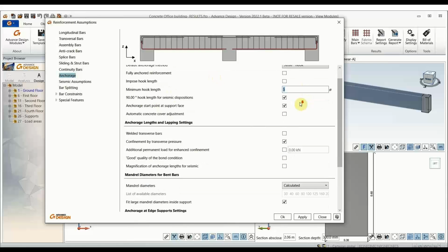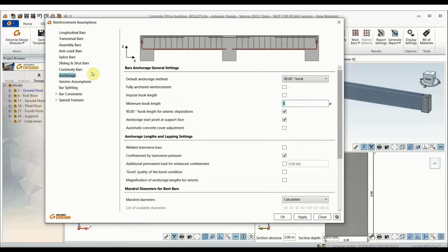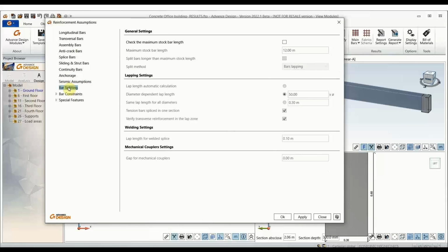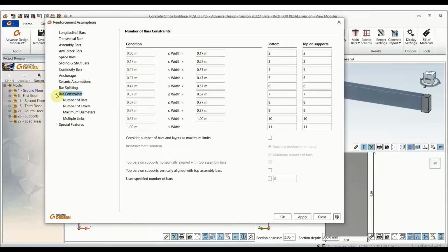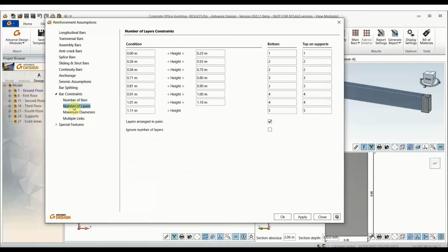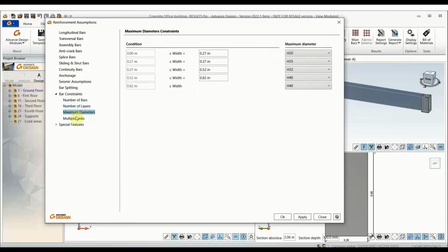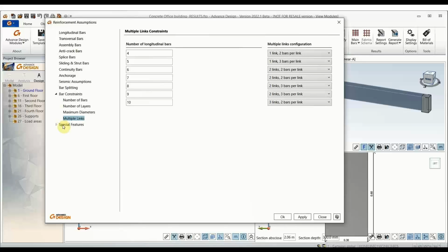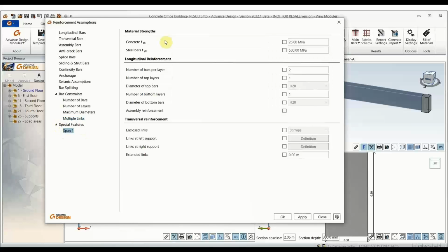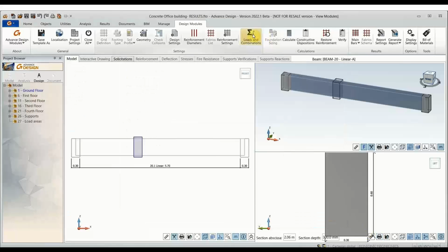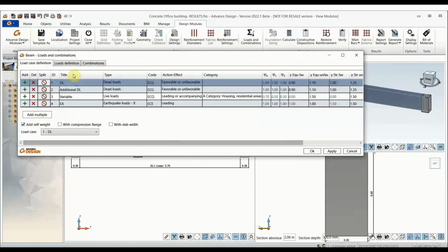And the good thing is, the design that you make in the design module, you can export back to Revit as well using the Power Pack. So your technician or the detailer can pick up the design that you've made for that member, and they can go ahead and start detailing based on that. They can then modify those cages. So all the reinforcement cages are exported across to Revit. They can then simply amend those cages as and when required.